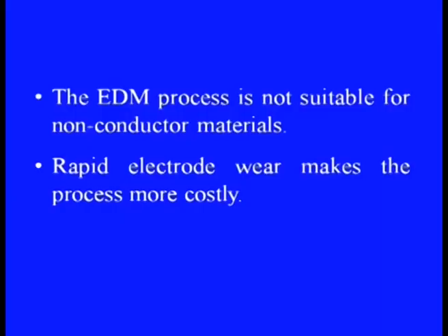Recast layers and micro cracks are inherent features of this process, and this makes the surface quality of the machined surface poor. The EDM process is not suitable for non-conducting materials. Rapid electrode wear makes the process more costly. This also we have already discussed.